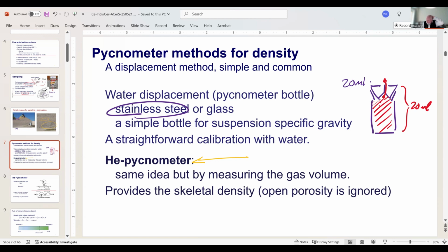Okay. If you want to measure the specific gravity, you can do that in a simple bottle. If you take a small neck bottle, typically, and you fill this with water, you weigh the bottle first, fill it with water, and then you know the volume, because the water is 1 gram per cubic centimeter. You can then pour your suspension in the bottle, screed off the top, measure the mass, and you have your specific gravity. So it's easy to calibrate. I had a student measuring packing densities years ago in a graduated cylinder, and he came back with data, and his data was interesting.